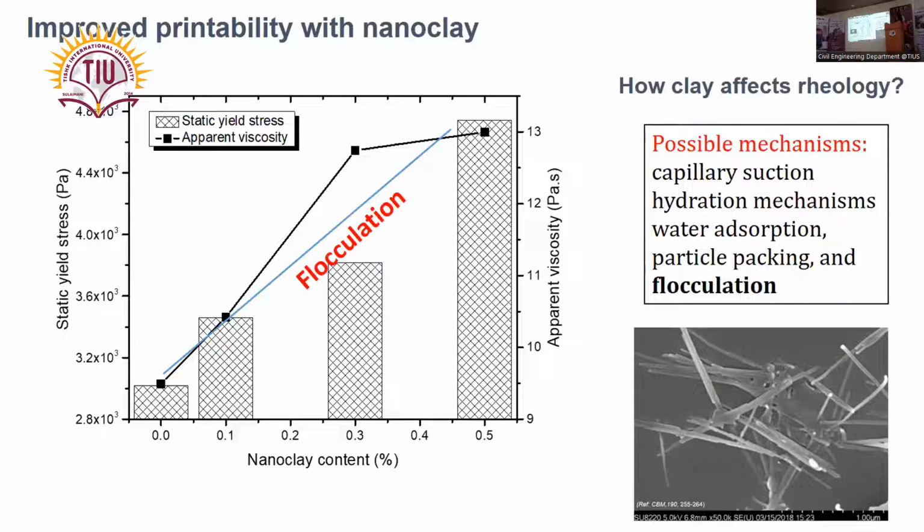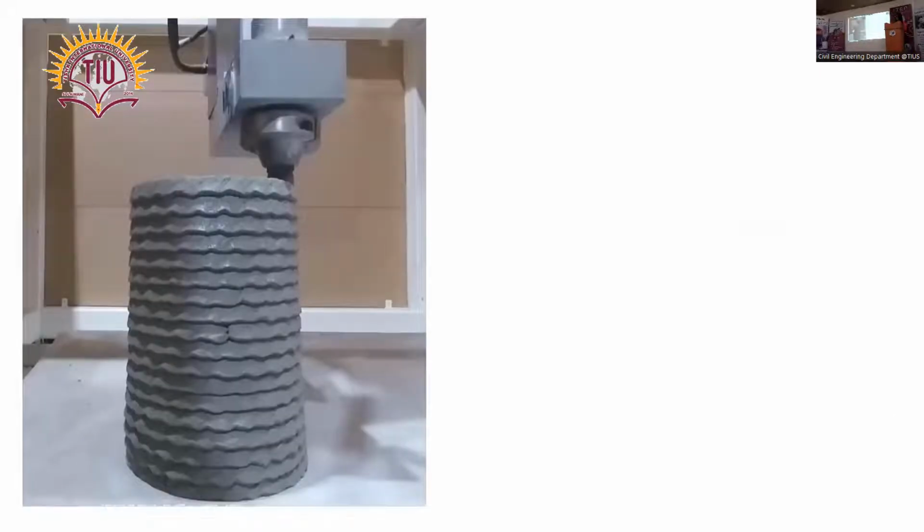So when you're going to pump this material, we should not cross a certain limit of yield stress, or else pumping will be very difficult for us. So with this improved material, we are able to print more layers without any deformations.